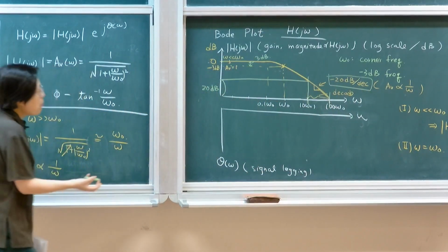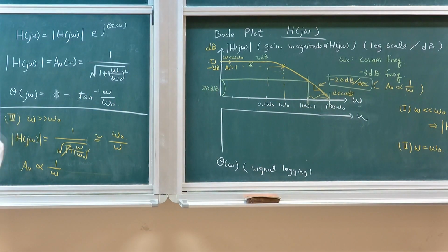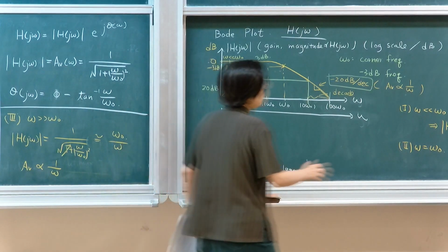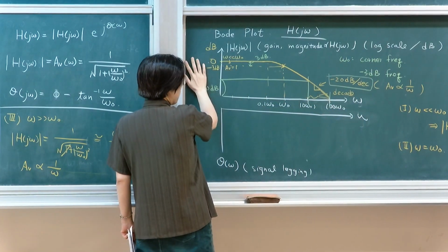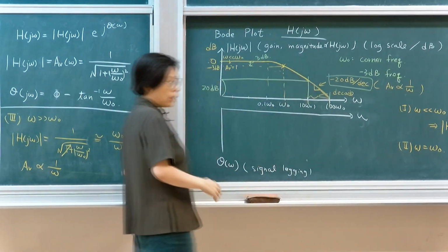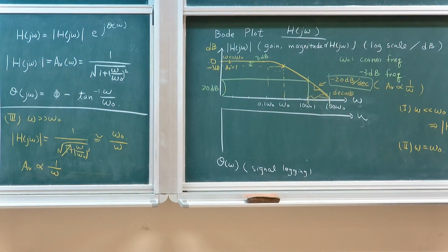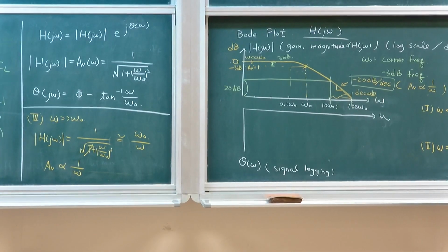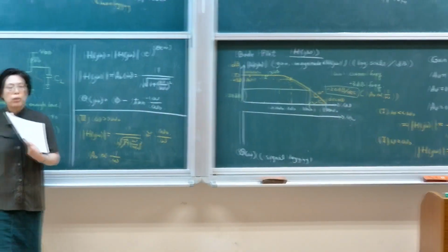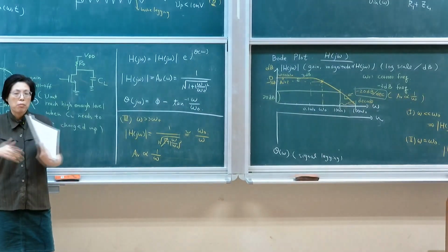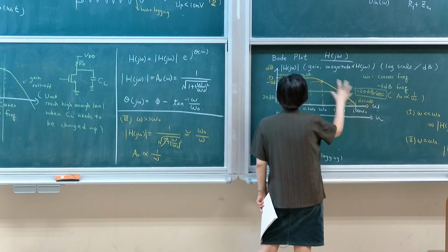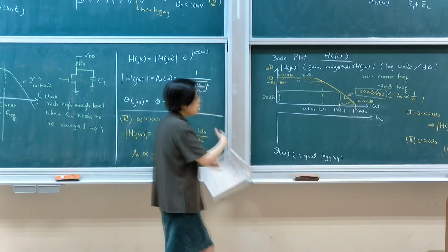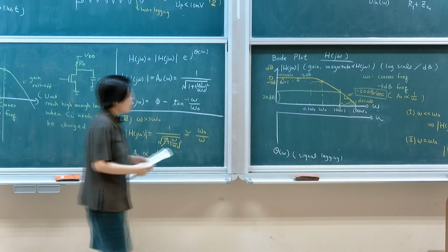Once you go through an example, you get a sense as to the Bode rules. We're going to come back to the Bode rules on Thursday. But just to give you a sense as to how one constructs this plot by finding extreme points, like very low frequency, very high frequency, and then the connecting transitional point. This is very much like when we do the transfer curve of a diode circuit. You look at extreme borders and then see what happens when it meets in the middle, the transition points. You find extreme levels and then transition points to connect the whole plot.